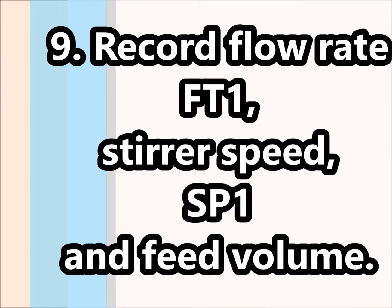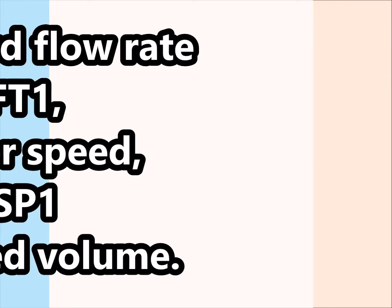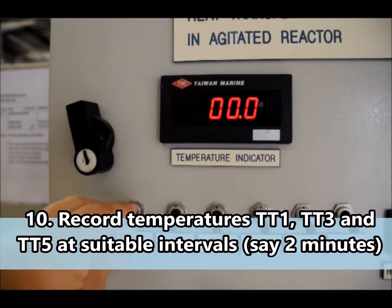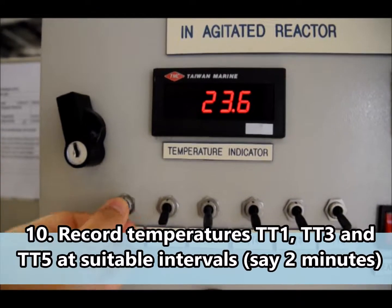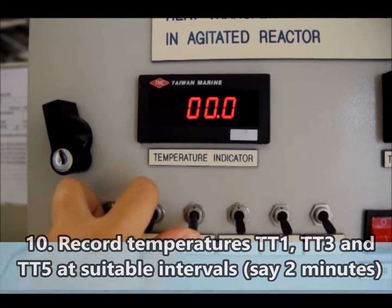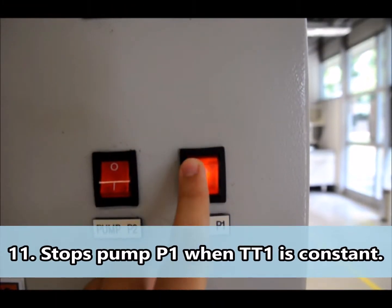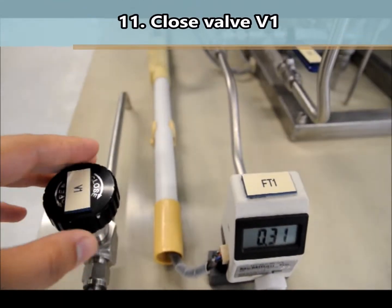Record flow rate FT1, stirrer speed SP1 and feed volume. Record temperatures of TT1, TT3 and TT5 at suitable intervals. Stop pump P1 when TT1 is constant. Close valve V1.